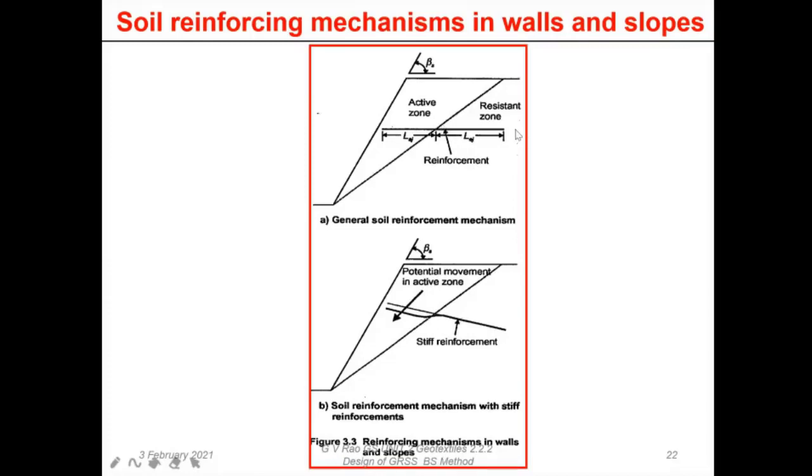So we are bothered about the tension along the plane, or a maximum tension which is going to occur at the junction between the active and passive zones. Okay. And then there is a minimum requirement for this, based upon many things. Whereas if you got a very stiff material as reinforcement, like let's say a rod also is reinforcement, in which case the stiffness of the rod is going to come into the picture. So that means the shear also is going to be coming out in favor now.